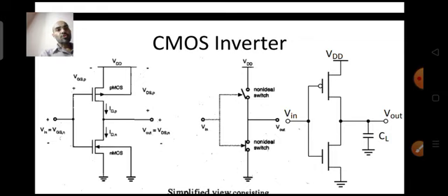If this switch is on, then the circuit will get completed. The Vout terminal will get connected to the ground terminal via the NMOS switch. That is important, because this path is required to discharge the output voltage, or the output capacitance. So it is the same as what we have seen earlier, whereas if you want to charge the circuit, then the opposite will be true.